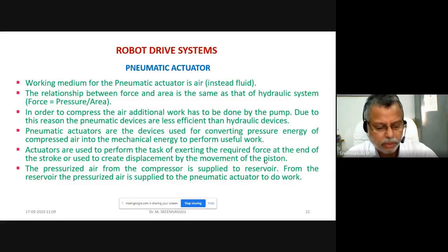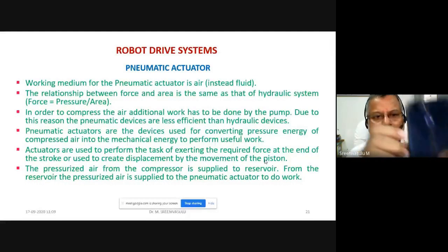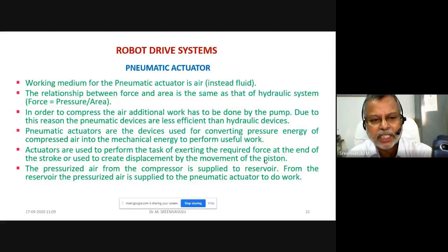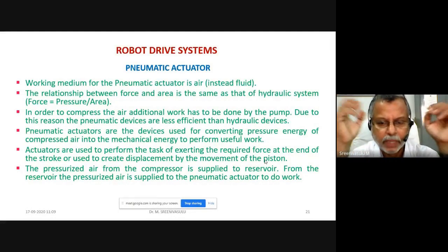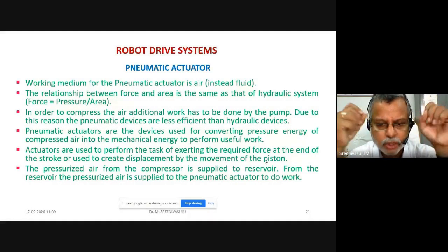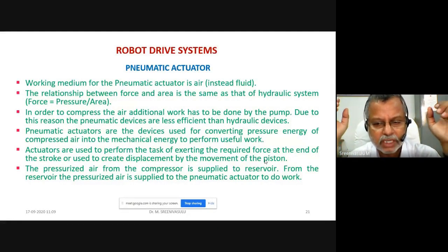There is no need for the end effectors to apply the same pressure on the component before they have got close to it. Soon after they have got close to it, at the instant of holding, only at that instant the force is needed. If it applies force right from the beginning, then throughout its travel that force is going to be applied on the object, and that is definitely going to spoil the object it is trying to handle.